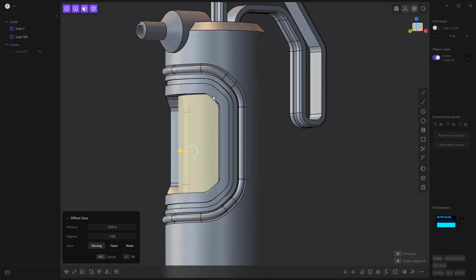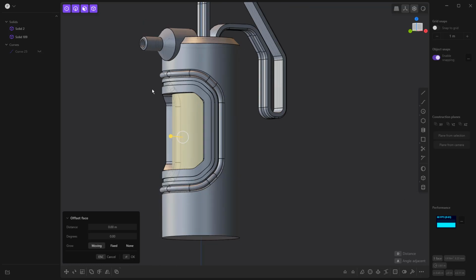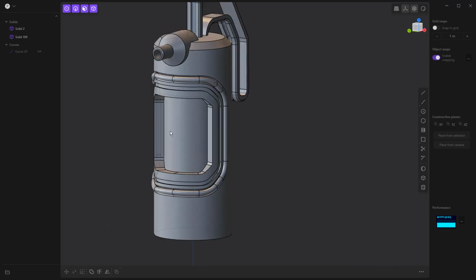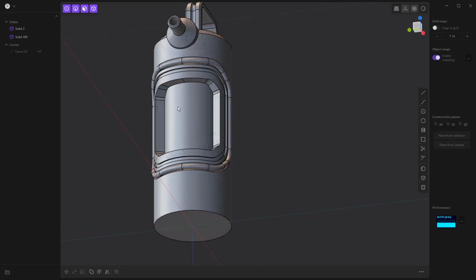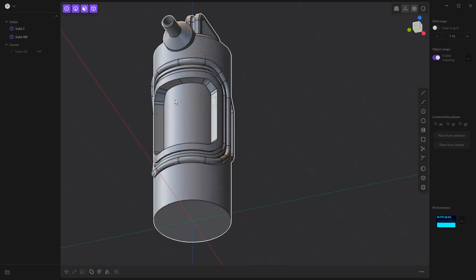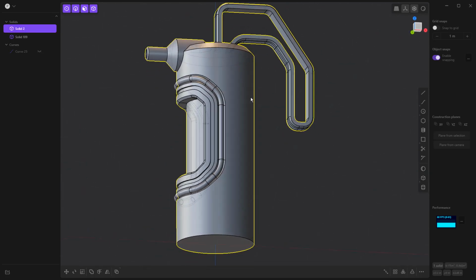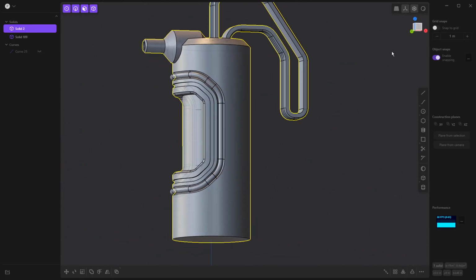Now, sometimes you might want to create this in a different way. Maybe you want to actually create a cylinder on the inside, completely delete or remove that, and create a separate solid body as a cylinder. You can totally do that as well. A lot of times these are just visual effects, and you don't really need a true multiple body part here. So you could combine everything together. But again, this gives us the option to add a fillet or a chamfer and just create those unique sort of paneled details. Let's go one step further on this.